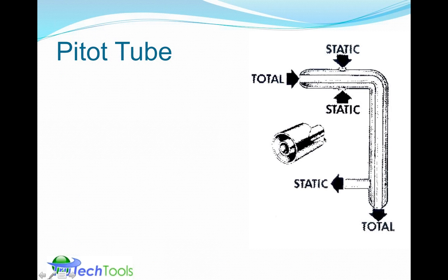They are not correcting. So let's take a look at another method, and this would be the pitot tube or the pitostatic tube. Here's basically a pitot tube. We talked about it being a tube within a tube. There's an outer channel, which picks up the static pressure of the duct. Imagine this being placed inside a duct. It picks up the static pressure of the duct only, and then the tip of the pitot tube has a hole in it leading straight down. That tube picks up the total pressure.